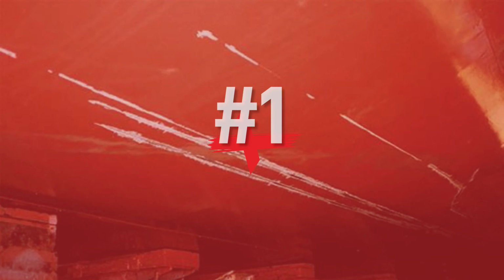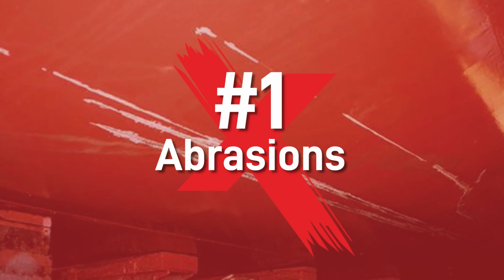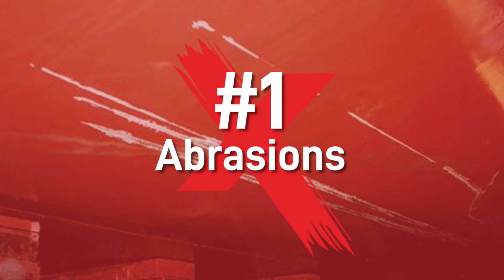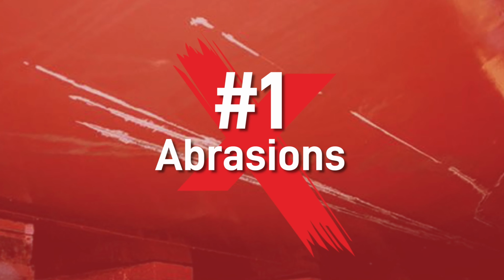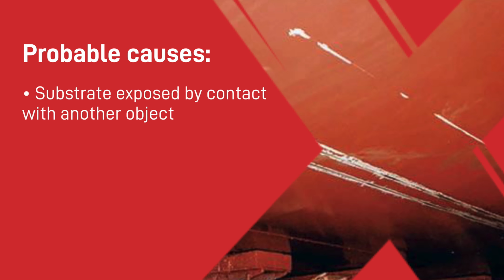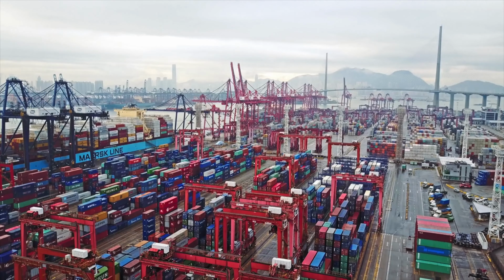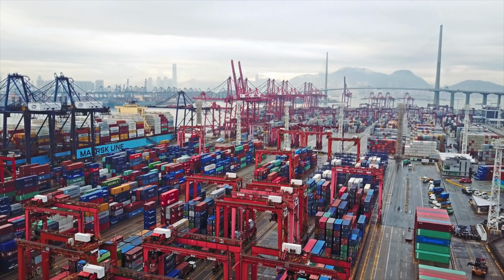So let's look at our first paint defect type, abrasions. Abrasion defects happen when a portion of the surface coating is damaged or, in severe cases, completely removed, exposing the original substrate. This often occurs through contact with another object, such as the use of metal chains for lifting, cargo scrapes, fenders, or even the grounding of a ship.